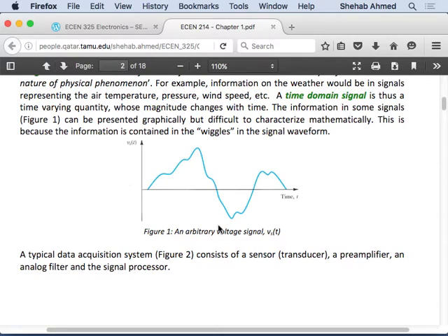If the signal has a 50 hertz component of voltage, and there's a linear circuit that it is connected to, it will produce a 50 hertz component of current, right? That's one of the unique things about sinusoidal signals: when applied to a linear circuit, they never change the frequency. That's why omega is always the same, and your omega t is always the same. So anytime you apply a sinusoidal signal to a linear circuit, no change in frequency will happen. I apply a voltage at 50 hertz, a current at 50 hertz will be produced.